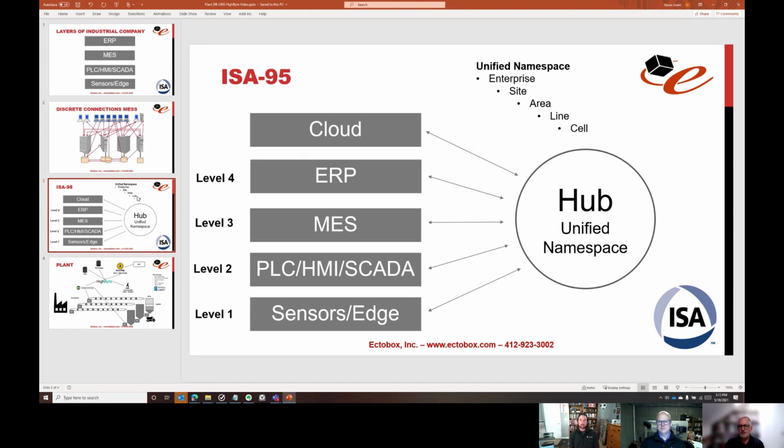But then once you want to start to share data between those applications, it's better to use a central hub, a central place to actually store that data. And that central place would be a data broker, and also at the same time to be able to use a unified namespace. You want one single place to put this data, to organize it. And so in this situation, we'd use the unified namespace. And the unified namespace is really meant to give structure to this data across the organization.